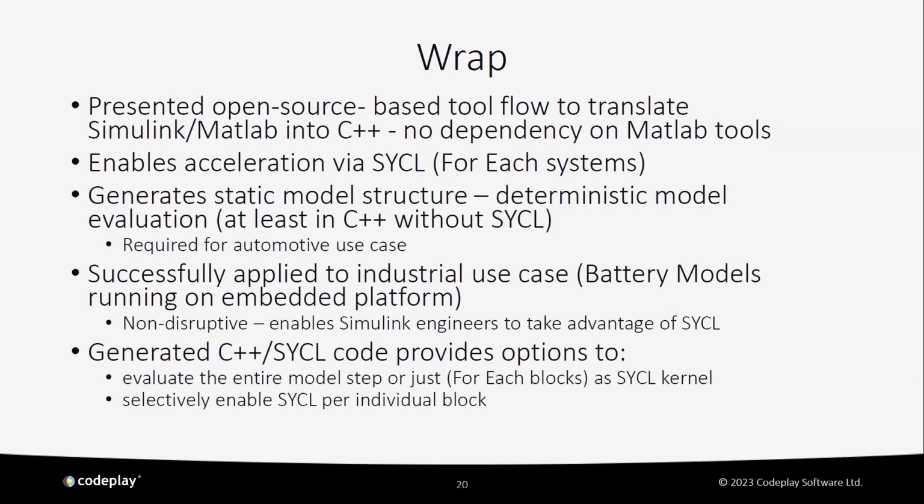It had to be really non-disruptive, because the Simulink engineers didn't have any experience with SYCL and didn't have time to look into this, and had to concentrate on their Simulink work. The generated C++ code provides different options to evaluate the entire model in different ways, either the entire model as model steps or individual blocks, so you can selectively enable SYCL per block.